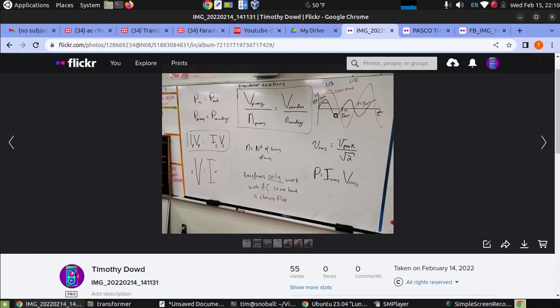One other thing, the average voltage in AC is 0 because it's varying between a peak and a valley, and basically there are 60 complete waves every second. So we have to find some other way to measure magnitude. This black sine wave here represents what power looks like in North America.